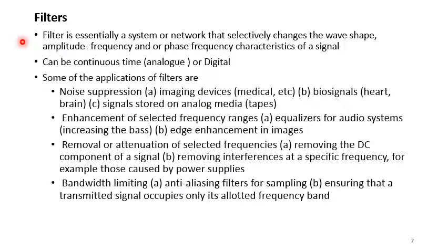And you have understanding that that can be a band pass filter that passes a band of frequencies and stops all the rest of the frequencies, or you have then the low pass filter that passes a frequency from DC up to a certain frequency that is called the cutoff frequency. Beyond that, it removes or stops those signals from coming.